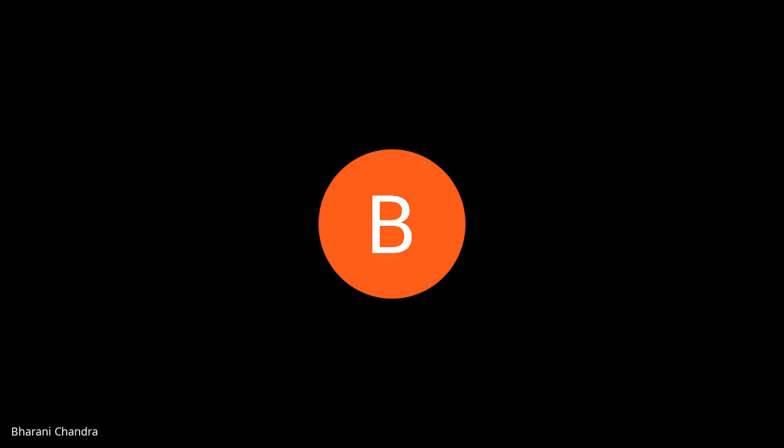Okay. I'm not a big fan of fuzzy logic control, but in general, for example, we have worked on fuzzy logic for a PID controller for a brushless DC motor. There is a standard tool available in MATLAB where one has to give some fuzzy rules, for example based upon Mamdani, or there are various other methods available. It will give you the PID gains, and whatever fuzzy controller you have developed using the rules, it will ensure that it works in all the operating regions.